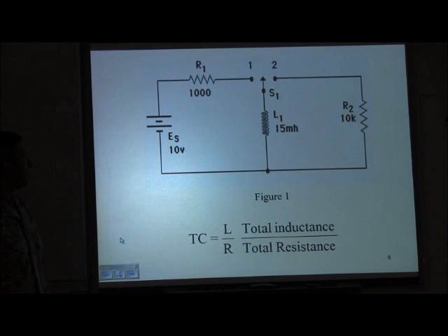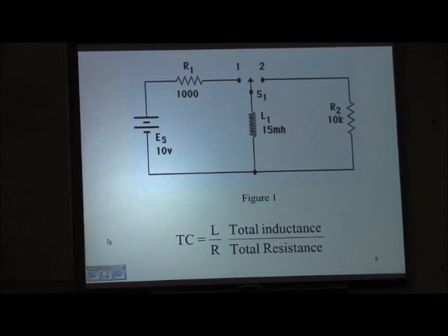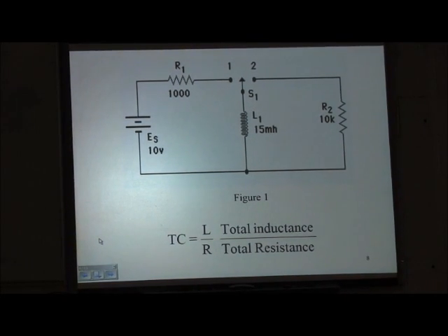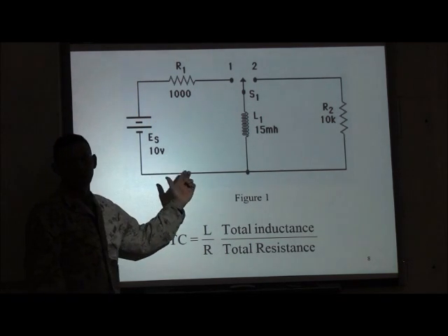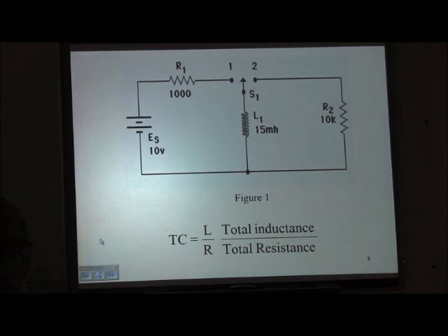Okay. First, you've got to get a time constant for each loop. Unless we ask you, hey, what's happening at the fifth time constant? Then you know what happens: it's either 0 or max. What's happening at the fourth time constant? There's really no need to calculate your time constant. Just take the natural number e, raise it to the -4, or whatever time constant we're giving you, right? If you want to do the math, knock yourselves out. Okay.